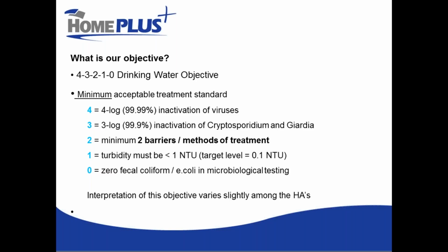Now, one thing that is important to note is that this objective, while seemingly relatively precise, does leave some room for interpretation. And there are some minor interpretive differences between the various health authorities in the province, particularly as it relates to the first requirement for 4-log inactivation of viruses.